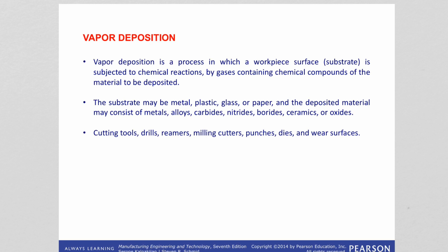And coating thicknesses can be very thin in this process, because you do deposition atomic layer by layer, you can control it. So the coating thickness is usually a few microns, and it will depend on the technique and the processing parameters you are employing, because there are a lot of processing parameters that you can play with to control the composition, thickness, porosity, and everything.